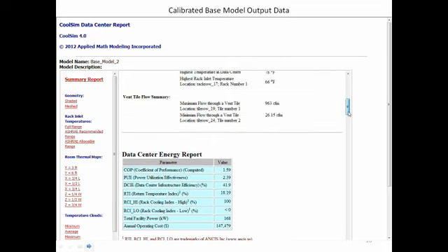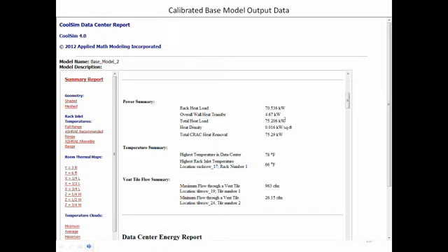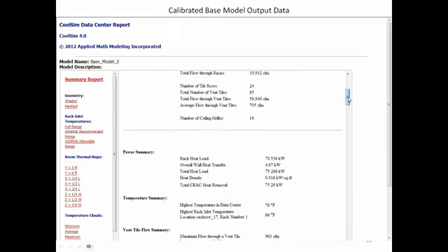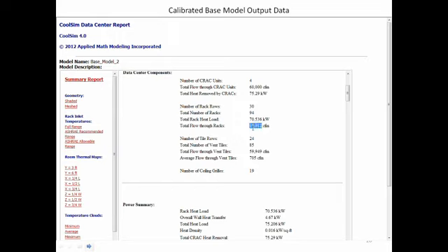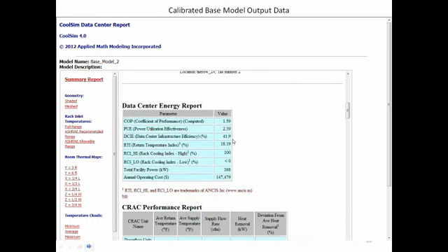Now, the reason that's true is if you take a look up here, we only have 70 kW of load. We've got some heat being transferred into the room, because we're running the room at 55 degrees. So we're cooling adjacent spaces. So we've got a total heat load of 75 kW. So normally that would want a total of 10,000 CFM, at least the 70 kW would. It'd want 10,000 CFM. But we're generating 60,000 CFM. So we're off here by a factor of 6. And that's what's driving this number so low.